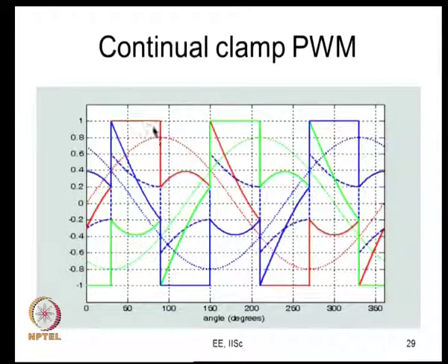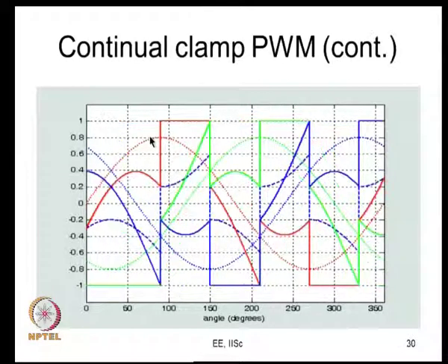So, here you will see that this is good, the switching loss will be lower if the power factor is leading. So, if the power factor is leading, let us say by 30 degrees, this will give the best switching loss, will give you the lowest switching loss. So, at other power factors, power factor angles between 0 to 30 degree lag, it is reasonably alright. Lagging power factor angles, this is not a very good idea, whereas this is a very good idea for lagging power factor angles. For lagging power factor angle of 30 degrees, this gives the lowest switching loss for a given current amplitude.